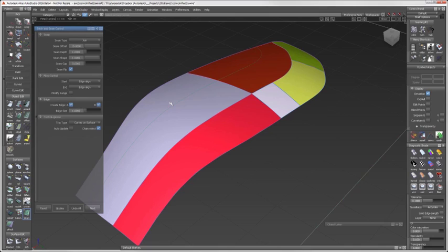We'll start by creating a seam on the curve on surface. Because I have chain select on, when I select the curve on surface, the complete curve is selected. Hitting the spacebar for both select and build creates my seam. The white and blue arrow show me the direction of the seam.